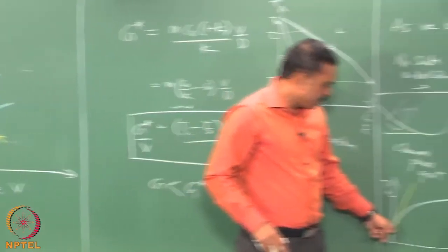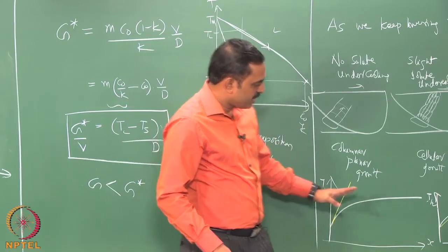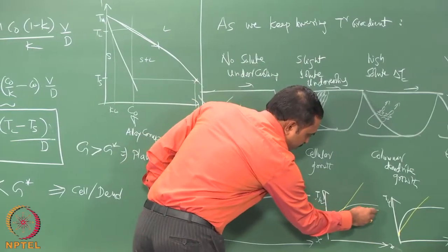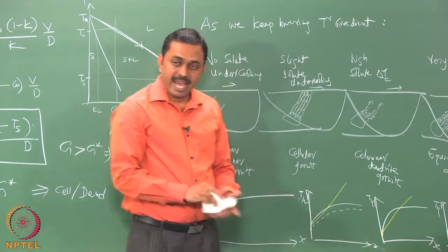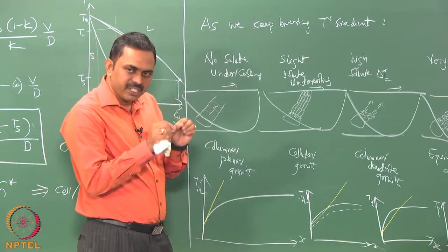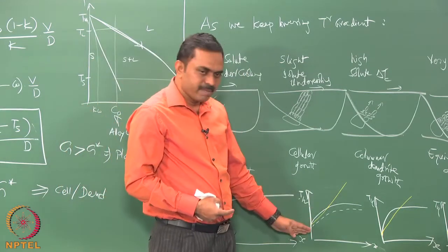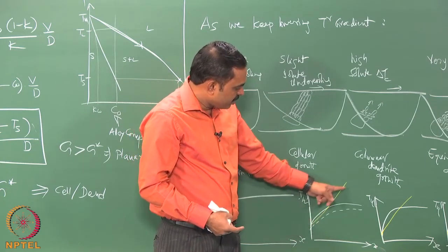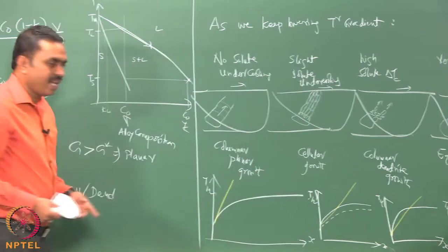as you can see here, the melting point, if it were to come down because of the curvature effect, then what was actually giving you some undercooling, if the plot is going to come down, then you no longer have that undercooling, which means that the effect of the undercooling which happens because of a fine curvature effect, that is at the interface, the surface tension effect is going to basically reduce the temperature of melting of any solid, and if that is significant, then what was a temperature gradient that would give you an undercooling will no longer give you that, which means that the surface tension is going to play a stabilizing effect.